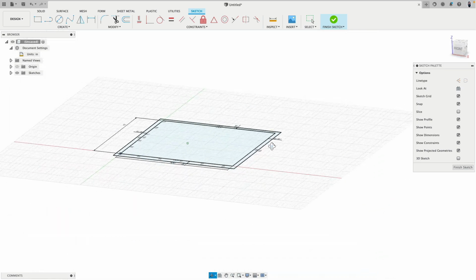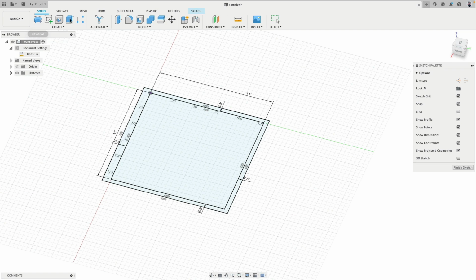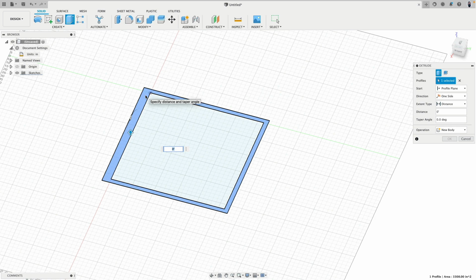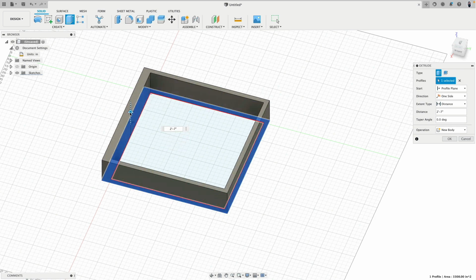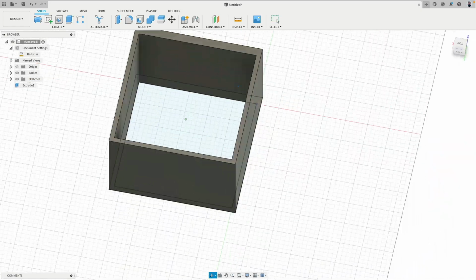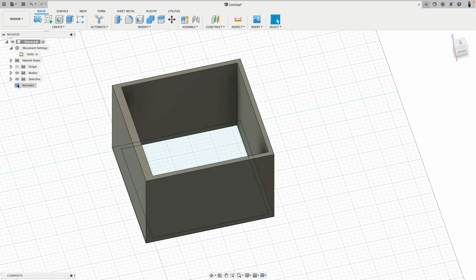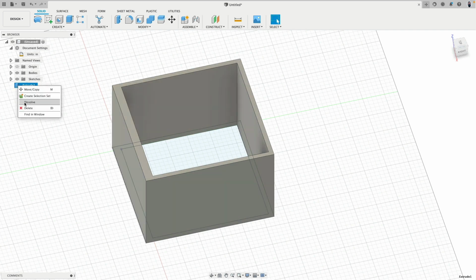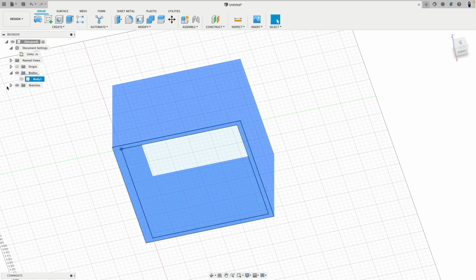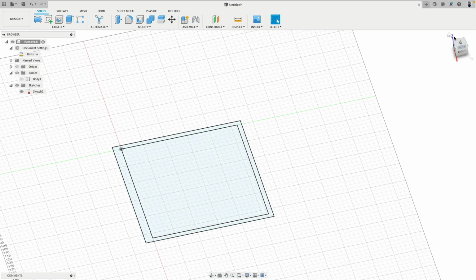We could then actually at this point extrude our walls if we want to. So here's the extrude command. There is the profile of the wall, and we extrude this up 8 feet. So it's pretty tall, as you can see. Very good. Here I have an extrude function. I right click and say dissolve, and here is the body for the wall. I hide this. I can open the sketch. Here's the sketch for the architectural space.